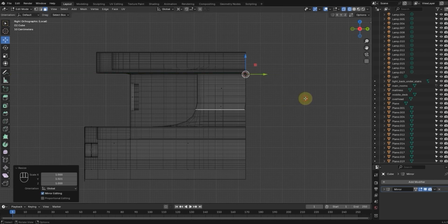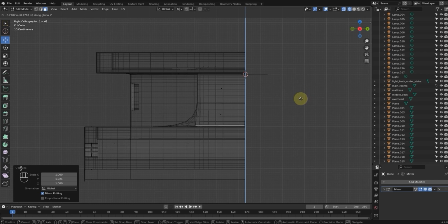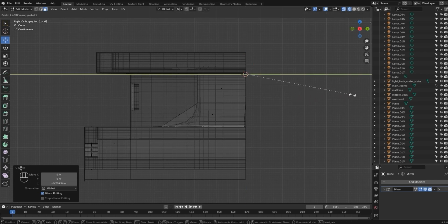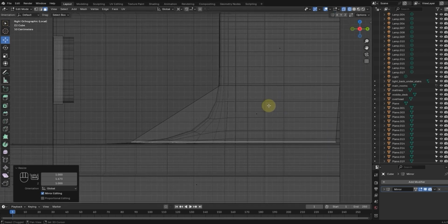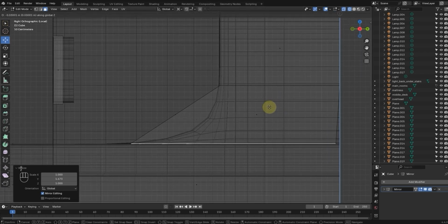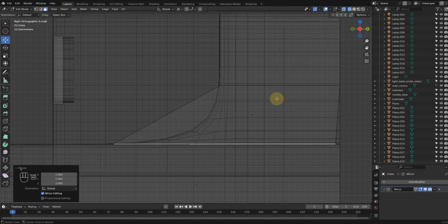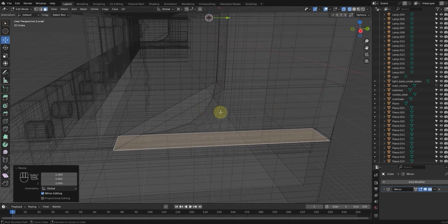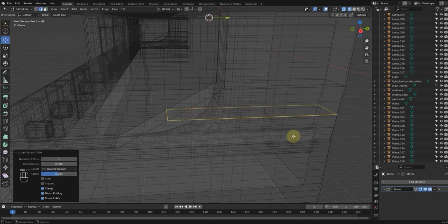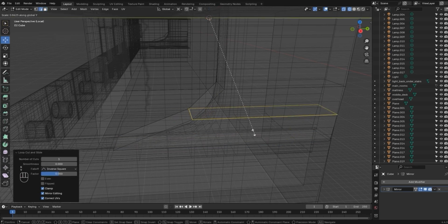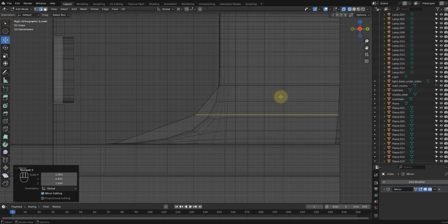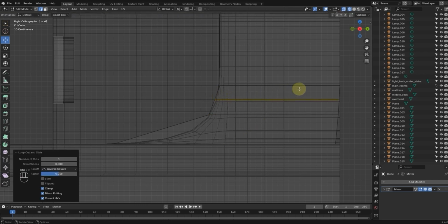You notice there that it's actually dragging as well. It's pulling the entire layer towards the front on the back. So I'm just going to do that again and stretch it just to reach that front there. And the next thing I'll need to do is apply loop cuts. I still need to get the length right. The next thing I'll do is apply loop cuts and scale on the y-axis only, reducing the size of the loop cut so it matches the curvature of the main wall.